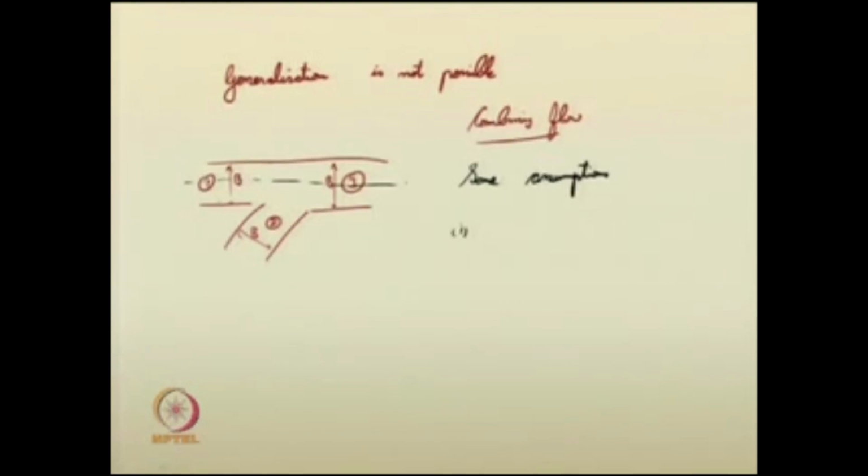This is also one assumption. We are neglecting the wall friction, and depths in channel 1 and channel 2 are equal immediately above the junction. Say around this junction portion, the depth of flow of this channel as well as channel 1 are both the same.